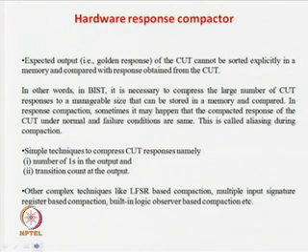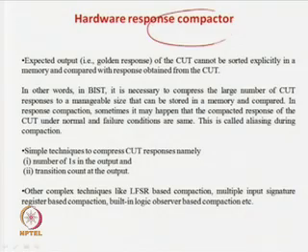Okay, now the second part of your BIST design. As I told you, BIST has 3 main components. First is the test controller that controls this one. These are standard digital electronics fundamentals: how can you control your circuit? That is the control path design. Next was your standard test pattern generator, which you have already solved using the LFSRs, that is the modular LFSR and standard LFSR. Now the remaining part is called the response compactor or response comparator.